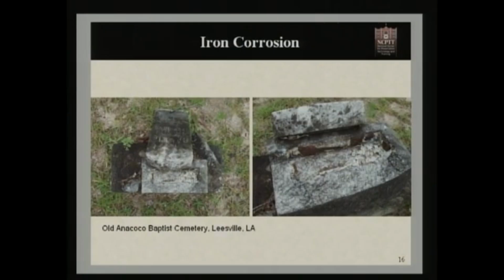Here we see a grave marker in Old Anacoco Baptist Cemetery in Leesville, Louisiana. For some reason, the grave marker itself was shimmed into the base of the stone with iron shims, not the more commonly used lead shims. When that iron expanded, it literally drove the base apart and caused the loss of surface and loss of integrity of the stone. When that happened, the base failed and the grave marker fell.